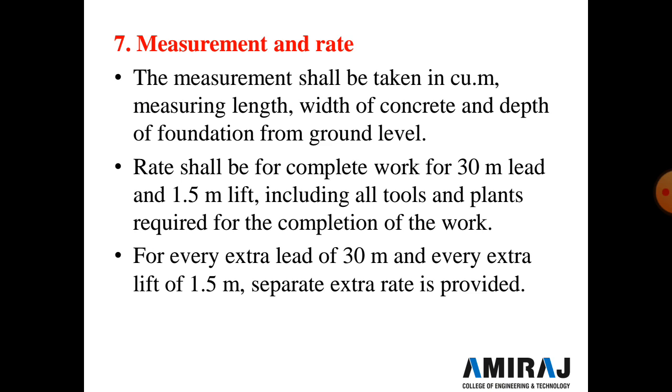Now seventh is measurements and rate. The measurements shall be taken in cubic meters, measuring length, width of the concrete and depth of foundation from the ground level. The rate shall be for the complete work of 30 meter lead and 1.5 meter lift, including all the tools and plant required for completion of the work, and for every extra lead of 30 meters and every extra lift of 1.5 meters, a separate extra rate is provided. So these are the important specifications given for earthwork in excavation for a foundation.